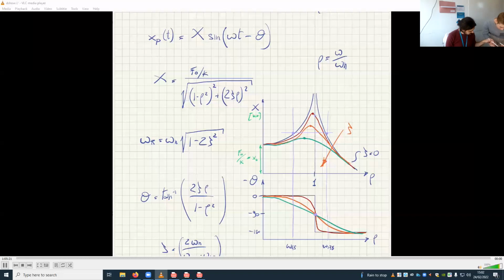Because if sigma a is the same as sigma e, this is already 1. So you can't have any more mean stress. This must be 0. If sigma a is the same as sigma e, that's 1 already. Sigma m must be 0. See what I mean? So sigma a is sigma e only when sigma m is 0, because that's the formula.